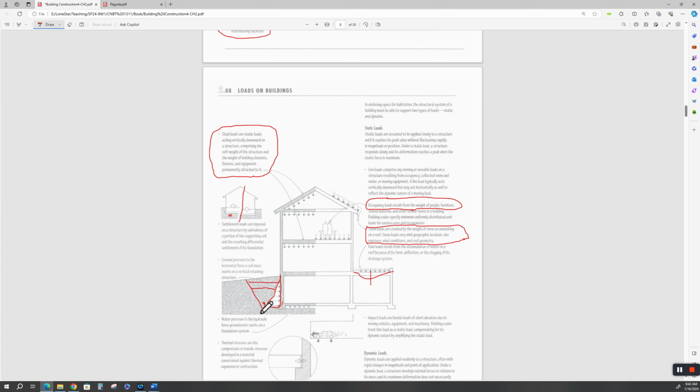And to do that, you're going to do it in benches. You're going to bench backfill this thing. You just can't throw dirt in there and run a bunch of little feet around there to stomp it down. You got to mechanically compact all of this. You might use a roller compactor, vibratory compactor, a roller on a machine, hand skid compactors. Run big equipment in here to compact this depending on how big this is.